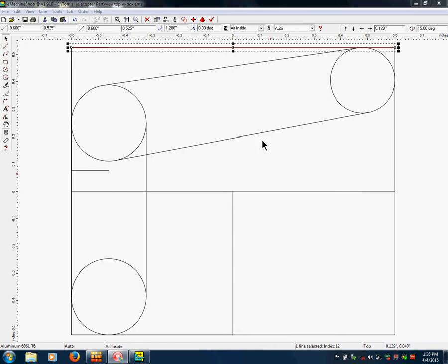The operation, the cut will actually be coming down from this direction, and this view is to find the depth. So I want to cut below this actual line. It'll start up the top and work its way down through the part sideways here, and I want to go beyond the point of this profile. So I drew a box in here and then deleted off the line. So I need to know this top level, which is 0.525 above 0.